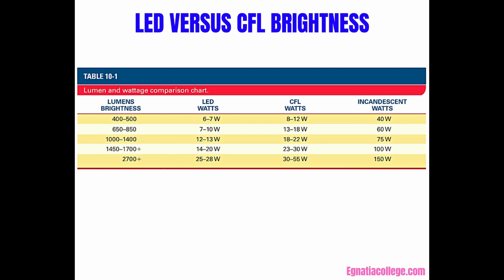The voltage on the circuit containing the LED is controlled such that the outer valence electrons in the semiconductor get excited to the point where they leave their orbital shell, but not so much that they can attain the next valence shell. The electrons are stranded between shells and must radiate their energy in the form of a photon so they can shed their excess energy and fall back down to their previous stable level.